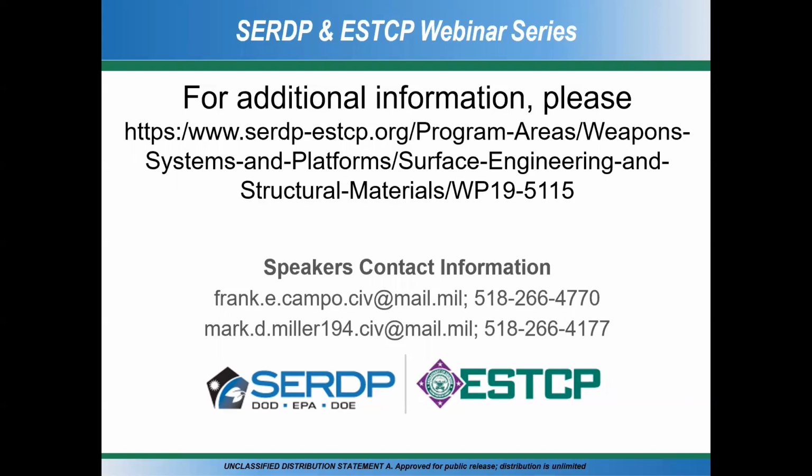Does the Waterjet technology use only high pressure water, or is there an abrasive in the jet? And if using an abrasive, can different abrasives be used? Yes, it is Waterjet and an abrasive, and you can change the abrasive, and different abrasives will give you different surface finish. It depends what you're looking for, how much material you want to remove, how concerned you are about the surface finish, but most definitely different abrasives are used.